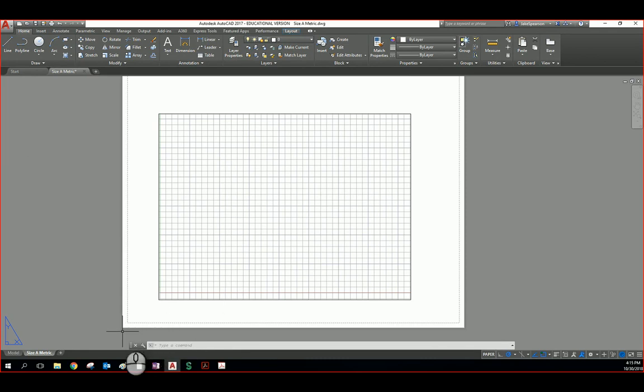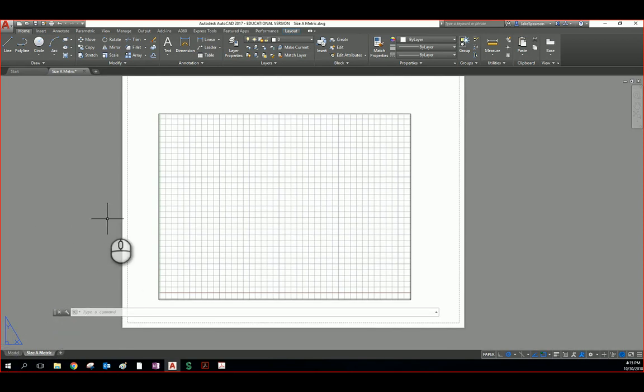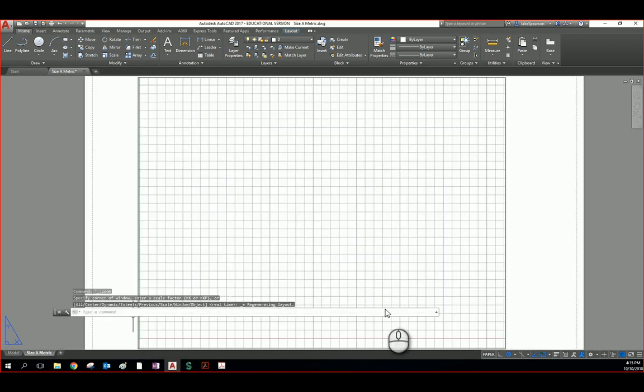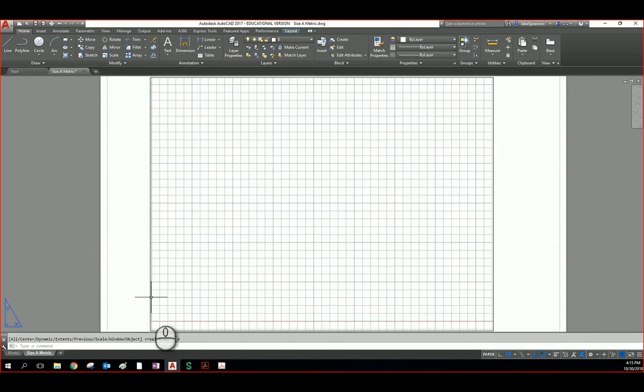two things that I always like, it's a pet peeve of mine when I come and look at a drawing, is if your command bar is not dropped down and taking up this space. And the reason why I say that, guys, is because if it's like this and I do a center mouse click twice, notice my command bar covers up this space, and I don't really like that. However, when it's brought down like this and I center mouse it, it gives me my entire view, and it doesn't allow me to be obstructed by this command bar.